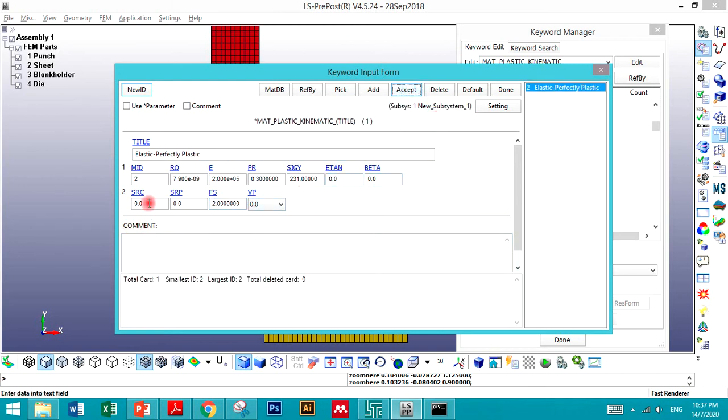Accept. The strain rate parameter is not important. Failure strain for this one is very important because of the shearing and fracture, so this is where the elements start to erode. They start to erode when the effective strain value reaches this failure strain value. That's what we get.